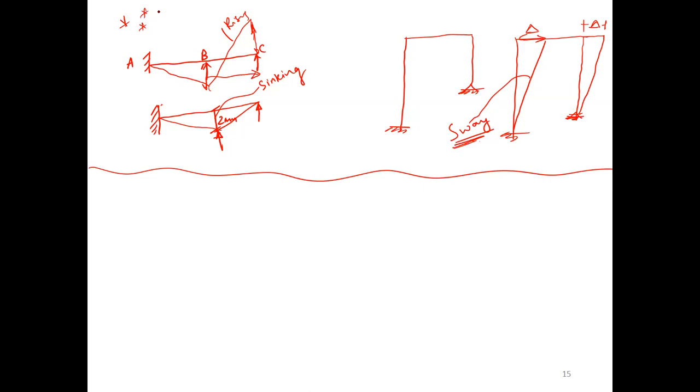Now sometimes they may ask an MCQ relevant to the equation. What is the equation? MAB equals MFAB plus 2EI by L, 2 theta A plus theta B minus 3 delta by L. Here there are so many things involved. I will try to give a few of the aspects. Okay, now you just observe here, sometimes an MCQ will appear, sometimes they may ask in an MCQ.